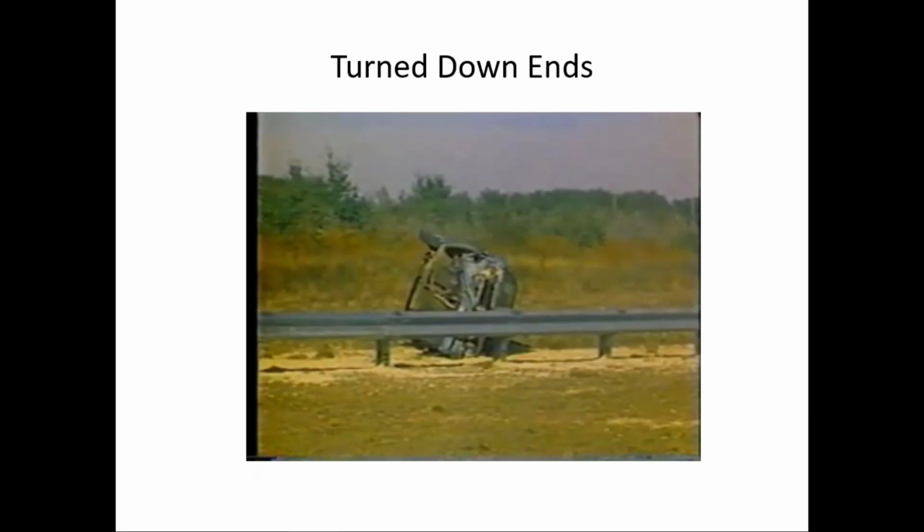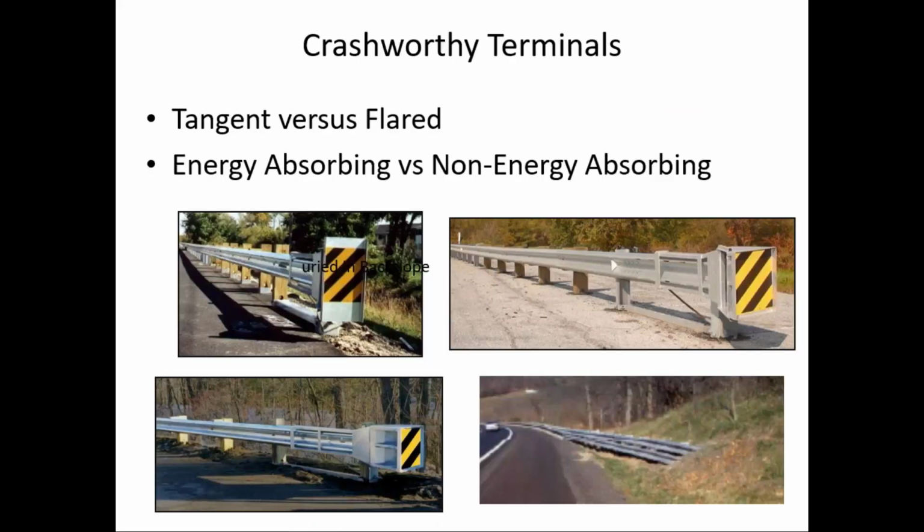So like I say, if you have any of those, it should be a priority to maybe remove or retrofit those. There are a number of crash-worthy terminals that are available. We're not going to get into the details of those, but some of the issues are tangent design versus flared, energy absorbing versus non-energy absorbing. But having crash-worthy terminals is important, both from a safety standpoint, but also from a risk management standpoint in helping to defend tort claims.